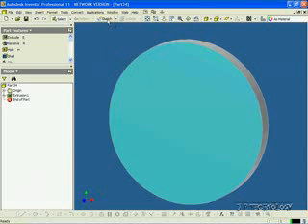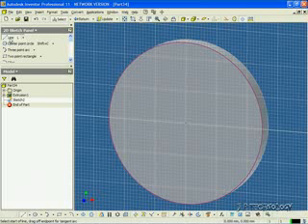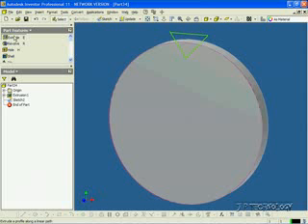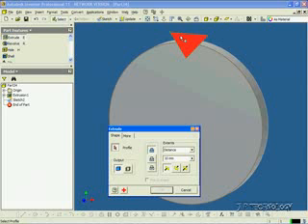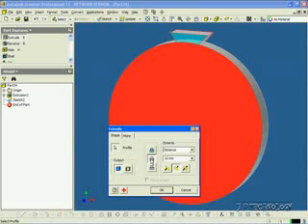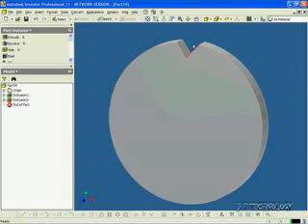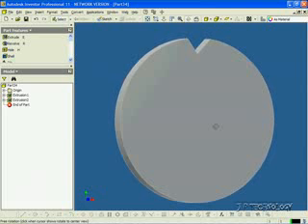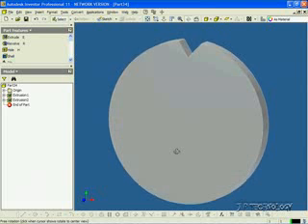So click the front face, click Sketch, and let's just, with the line tool, sketch a little triangle that's going to cut out the first tooth. So we've sketched our triangle. Now let's click Return, click Extrude, and we'll select the triangle that we just drew. We'll cut it out, click OK, and now we've made the first tooth of our gear. Now using this first tooth that we cut out, what we have to do is use a circular pattern to create it all the way around.